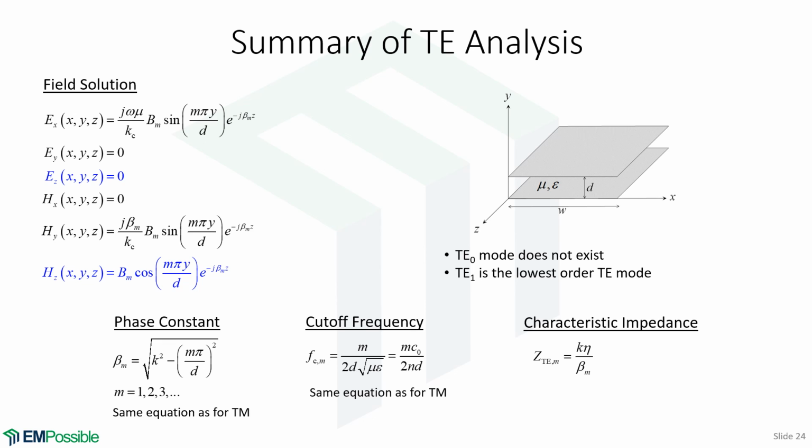And the lowest order mode is always the most important mode, because if we try to send power down the waveguide, most of the power ends up in the lower order mode. So that tends to be the one we work with the most. And a lot of times we only want a single mode to propagate in that guide. And why is that? That's because the modes travel at a different speed. So if we launch, let's say, the edge of a square wave and we excite both modes, if they travel at different speeds, that nice crisp square edge is going to blur and spread and cause bad problems. So very often we operate waveguides as single mode.